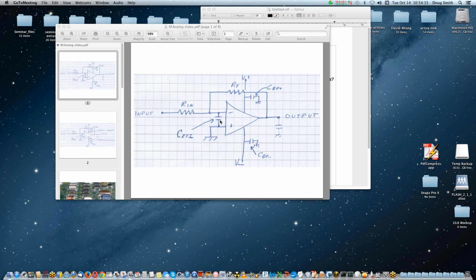What I would do if I were going to select a part, I would build a board with the ground plane as the second layer, or the bottom layer. It might just be a two-layer board, with ground on the one layer and all things over ground. Make my little op-amp circuit, say like this one here. Here's my input. I would monitor the output, with the input and output coming in through SMA connectors, right? And I might even have two inputs, the real one and my RF one that would come in through a resistor also.